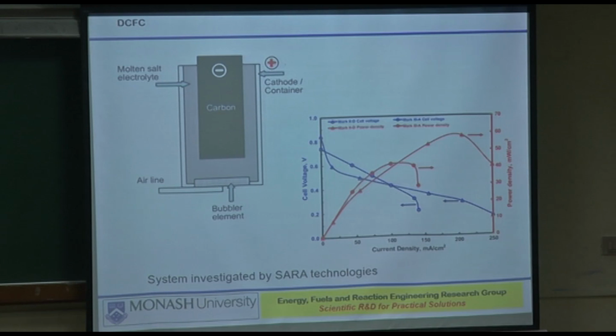So you can plot everything that is needed for characterizing the performance of a fuel cell, which are power density, current density, cell open voltage. Okay, these three, right? We have seen that before. And of course, behind all of this is the fuel utilization factor. How much fuel remains unutilized? That's something you can also find.